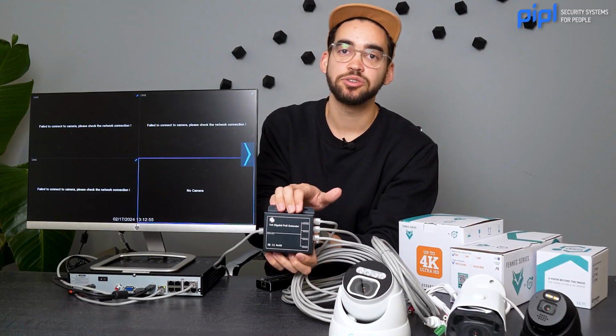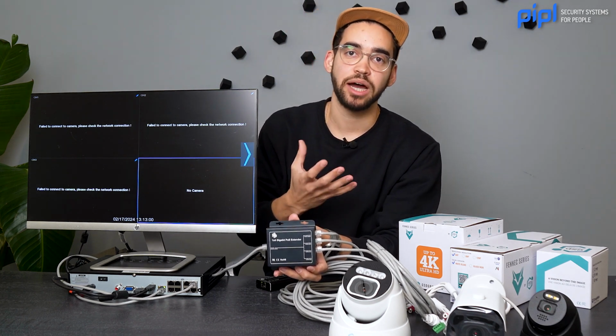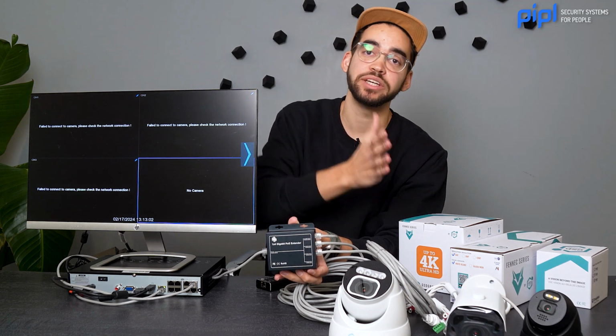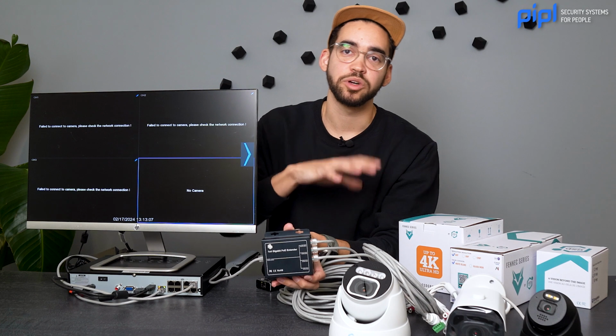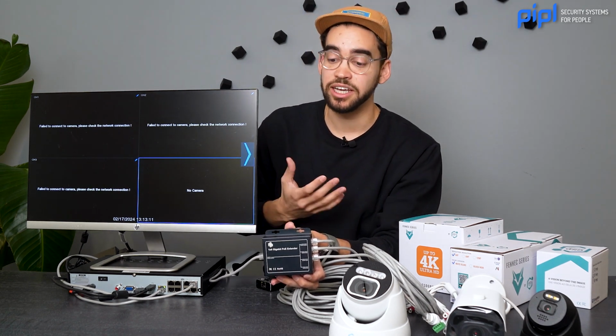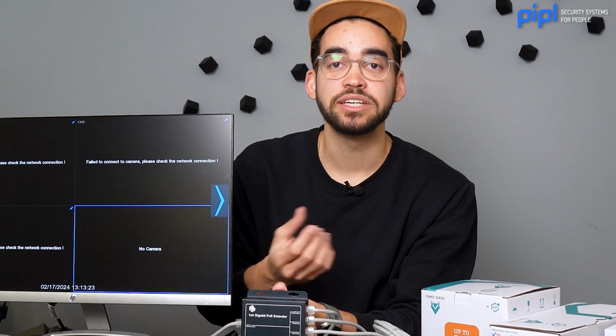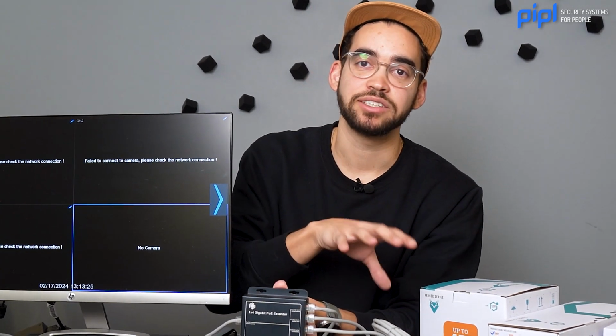Again, this is not to increase the number of channels on your NVR, it's to power up the cameras or give them a longer range distance from the NVR. So it's really useful when you're working on places where there's not many power outlets. And again, using this, you can power up not only cameras, but any kind of IP security solution. So this is how PoE works. It's power over Ethernet. It's a way to power up your devices rather than using a 12-volt DC output.